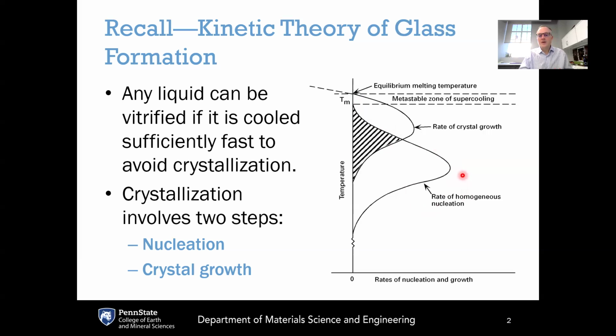However, if we are making a glass ceramic, we want to be able to control the amount of nucleation and crystal growth, and that would usually involve doing a first heat treatment here at this peak nucleation temperature in order to develop nuclei, or to develop a desired population of crystal nuclei within the glassy matrix itself. Now, the second process that leads to crystallization is the crystal growth process. Remember that crystallization occurs in two steps, where first there is nucleation, and once a stable nucleus forms, that stable nucleus can grow into a crystal via the crystal growth process.